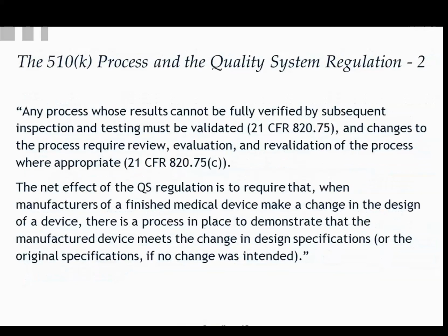Notice this point: any process whose results cannot be fully verified by subsequent inspection and testing must be validated. Now, I've seen the FDA really get tight on that principle to the point where even where you can fully verify a process, they sometimes require post-process validation of some kind of check and balance or pre-production and process control system in place.